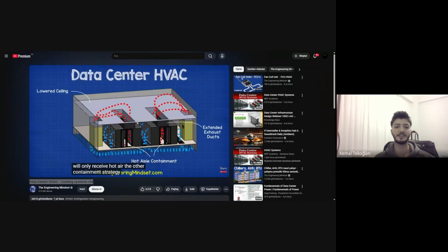The other containment strategy in use is the hot aisle containment. This is best suited to new builds as it costs more to install. In this strategy, the cold air fills the room and the hot discharge air is pushed into another void within the ceiling. The intake of the CRAC unit is also ducted into the ceiling to pull this hot air out for reconditioning. The hot aisle containment provides superior performance and also allows a slight buffer for cooling should the power or cooling system fail.